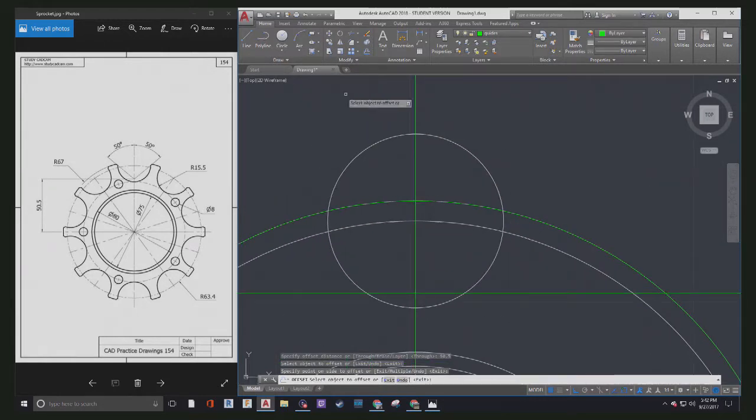And then now we can focus right here, and we can draw a line snapping from here. Turn off ortho if you had it on, and we're going to say 50 degrees from the center, but notice that my angle right here is referencing from the horizontal line. So I'm going to basically say 90, and if I want to come down 50, that means I have 40 left over, so I'm going to hit tab and say 40 and hit enter, and that's a 50-degree line from the top. I'm going to just mirror that over.